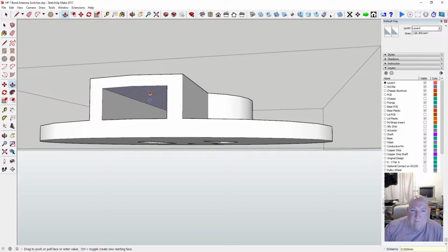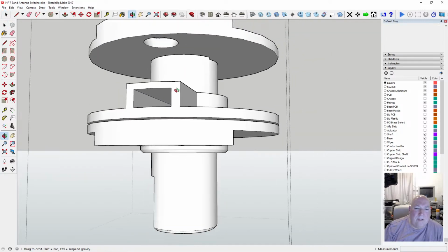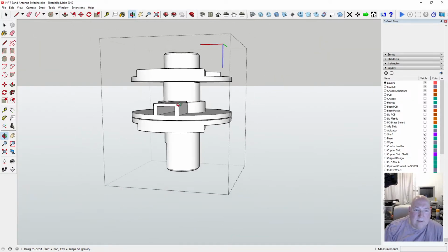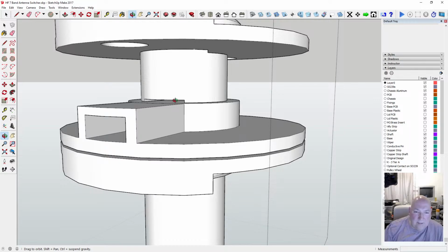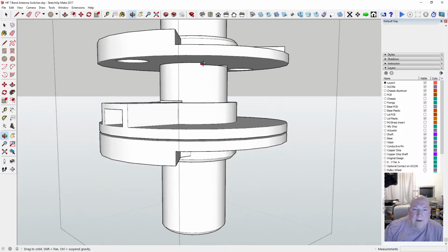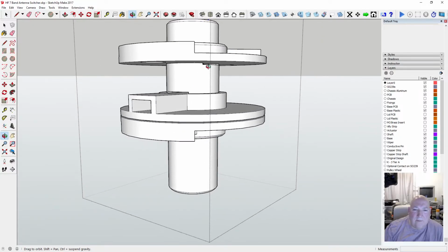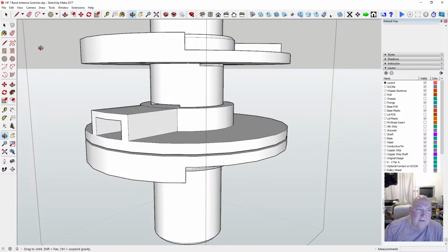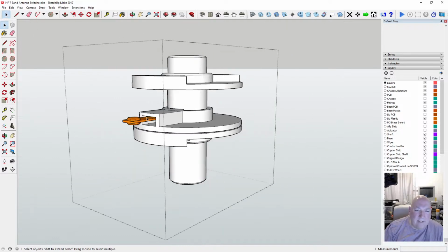So I'll go 0.5. When it was a one-piece shaft, you could work it out exactly, but it's this gap here, these bits of gaps, and that bit of gap there. It's not a known thing. Just push it together as close as you can get it, basically.